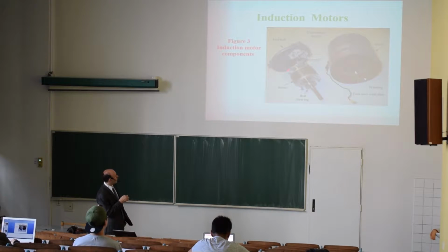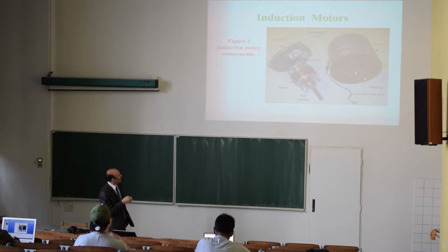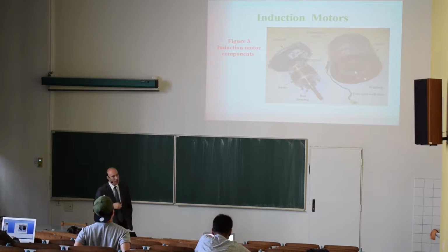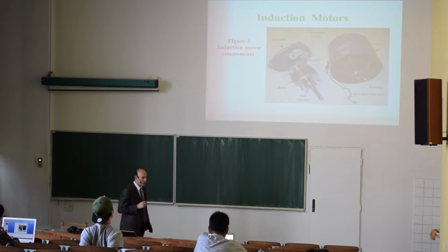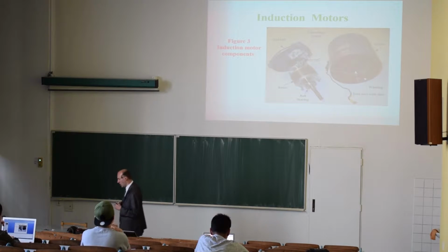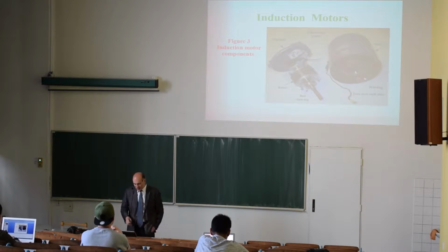So this is the rotor. As we will see in a few minutes, it is steel that is laminated. And the stator is equipped with windings, and it is also created by lamination. So the steel sheets are laminated, and in the case of a three-phase motor, it will have a three-phase winding. So the construction is completely different from the DC motor.